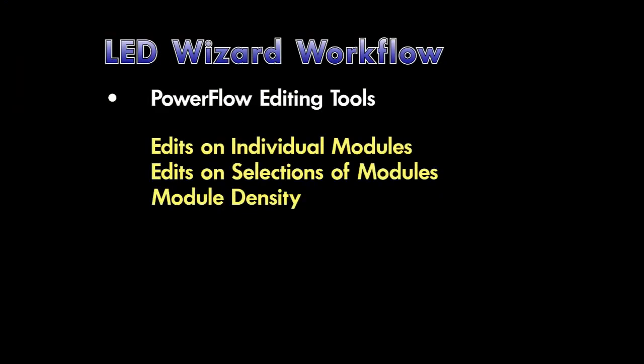Now a quick summary on PowerFlow editing tools. We talked about making edits on individual modules, such as adjusting the position on and off the guide path, rotation of modules, inserting modules, connecting runs, breaking runs. And then we talked about making selections of modules, and some of the edits we can make on a selection of modules, including increasing, decreasing density, evenly spacing the modules, and various rotation options. We also showed module density and the various readings we have to ensure that you have consistent module density across your letters. The next section we'll talk about adding power supplies.